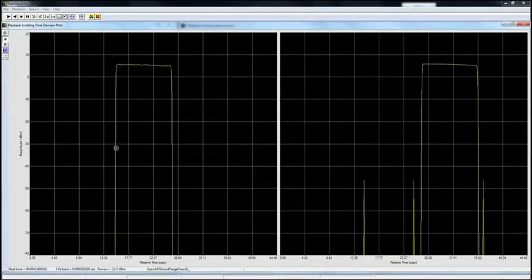Because the markers are 2-dimensional markers, in this case time and power, and we want to make a time difference measurement, we need to make sure that we are placing the markers at correspondingly equal power levels across the 2 windows. So Spectro-X provides certain visualization tools associated with the markers to make this a lot easier.